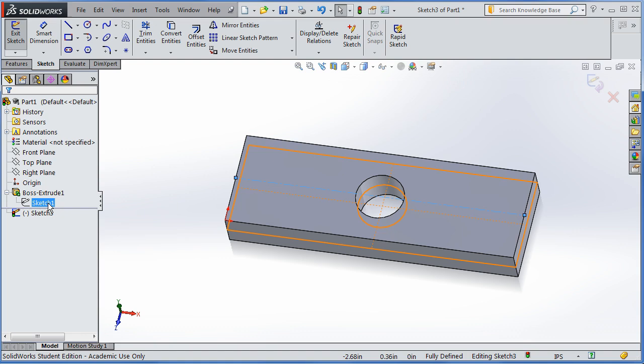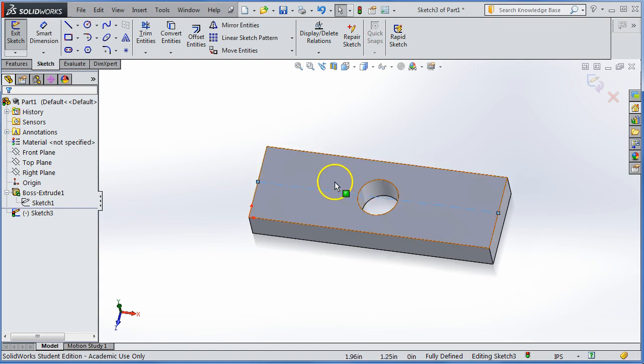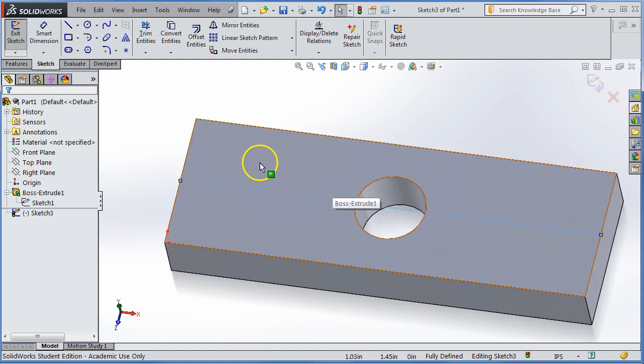There are ways to move that center line or to copy it up, and that certainly can be done, but it's technically not yet a part of Sketch 3. So that's simply the reason for that. So there's the center line, and say I want a circle that's centered on there, but a set distance away from that line. Okay, so let's try to do that.